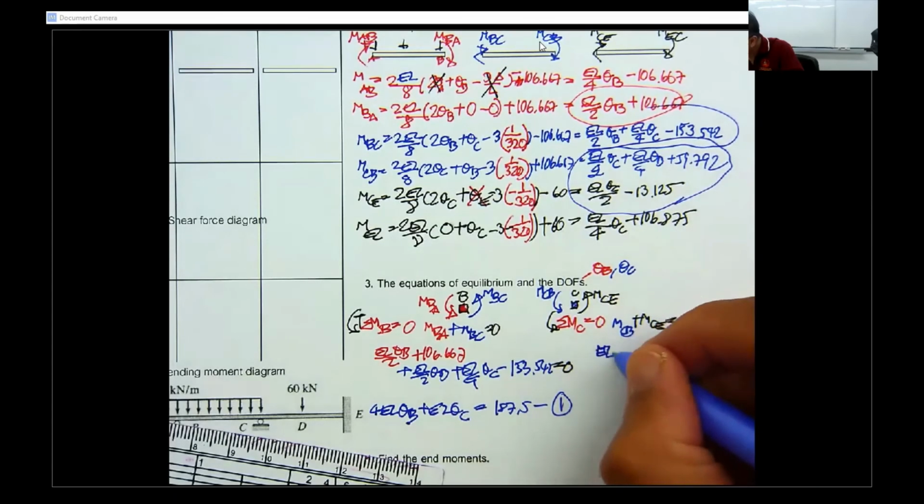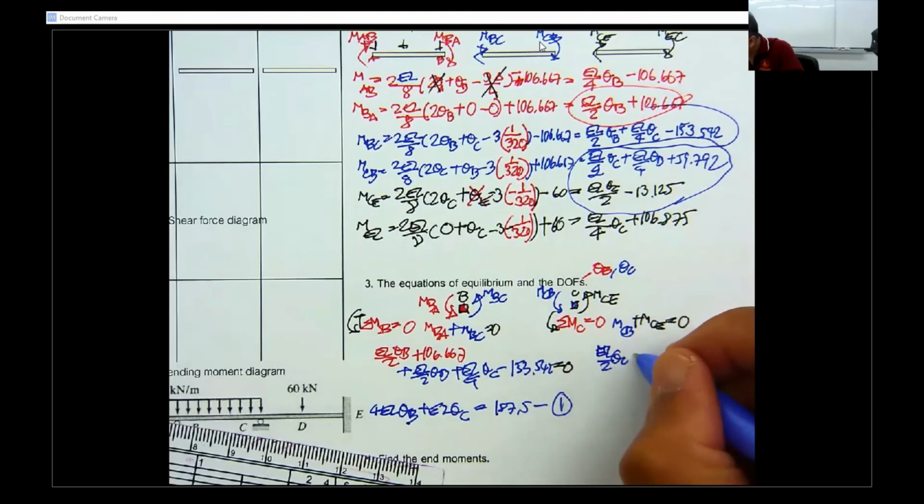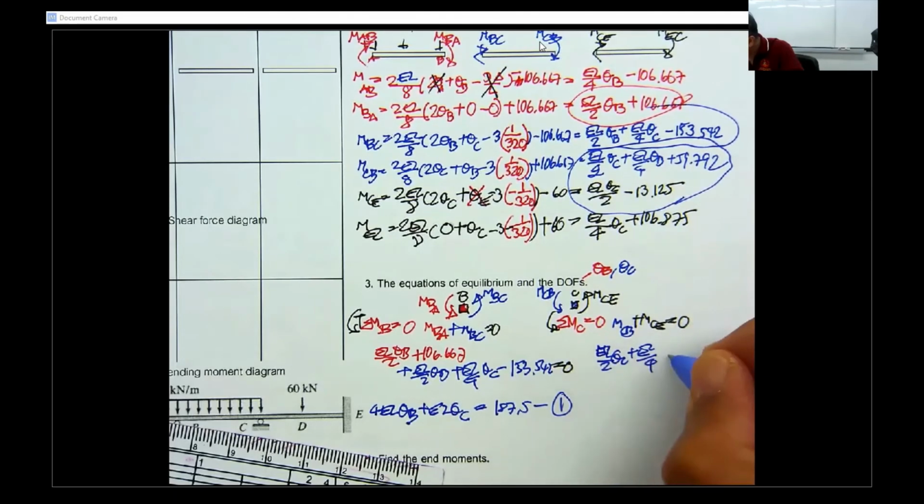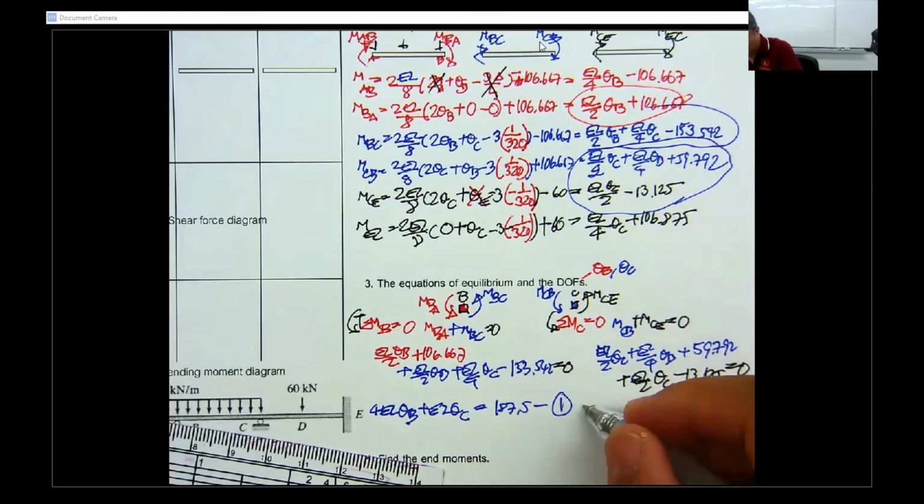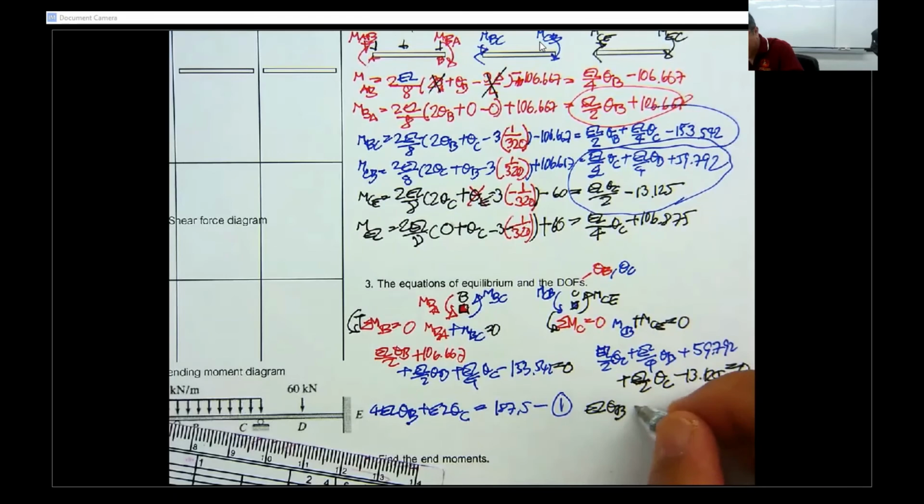This one, EI divided by 2 theta sub C plus EI divided by 4 theta sub B plus 59.792, and then you have this one plus EI divided by 2 theta sub C minus 13.125, and then equal to 0. You get the second equation, EI theta sub B plus 4EI theta sub C, and then you get this one equal to